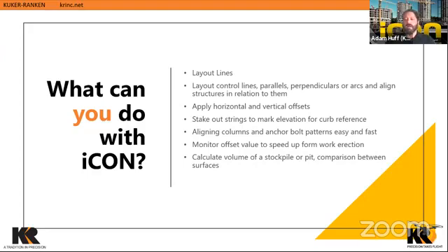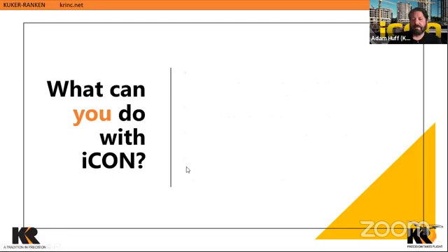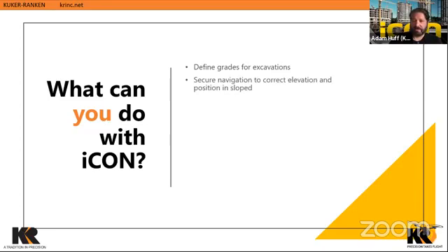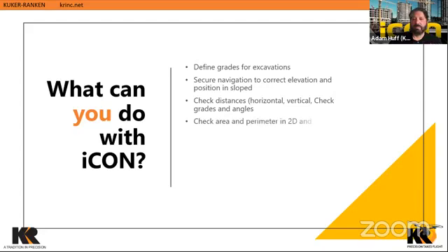You can also apply compaction factor relations for your materials. We can also define grades for excavations, get secure navigation to correct elevation and position in slope, check distances, horizontal and vertical grades, angles, and check area and perimeter in 2D and in 3D.